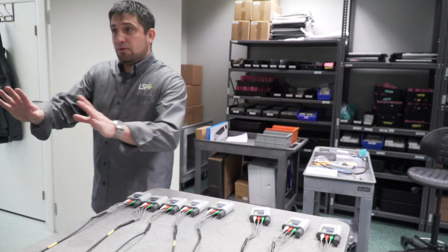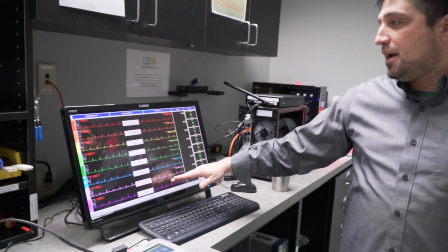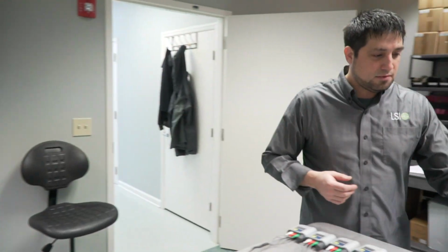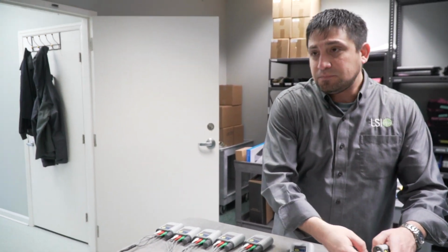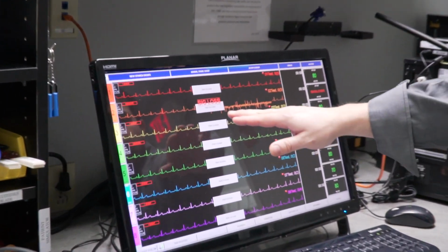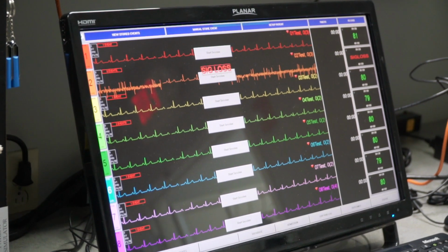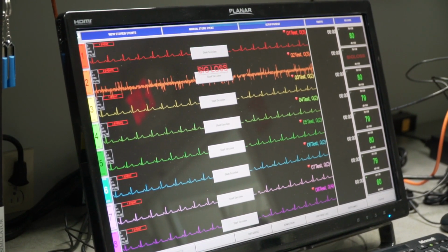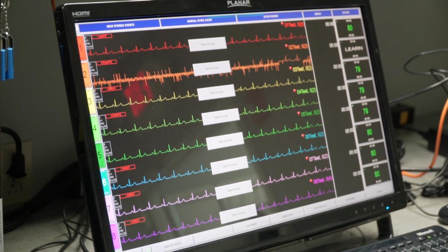And so we send all those out back onto this screen, and we have 8 results. So if I were to remove power from one of these transmitters, we would notice that we have sig loss. So it's basically saying we've lost transmission. So we're able to verify that individual channels are down. Now I'm going to put the cap back on and we'll see the signal come back.